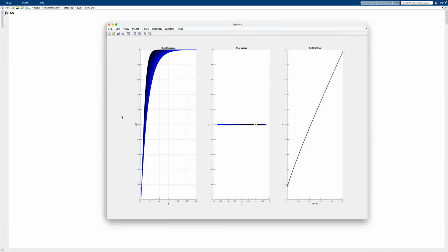Now, arguably, we're seeing first order system behavior because there's no overshoot. The more we go to the left, supposedly, we're actually also going to the right, but this one is dominating the behavior. It seems like we become slower and slower, which aligns with the fact that this part is dominant. We see that the settling time increases, the amount of time that we have to wait increases, and the system becomes slower. Now, this is an interesting system, and most of the time we don't use overdamped systems for design purposes. And the reason is the following.